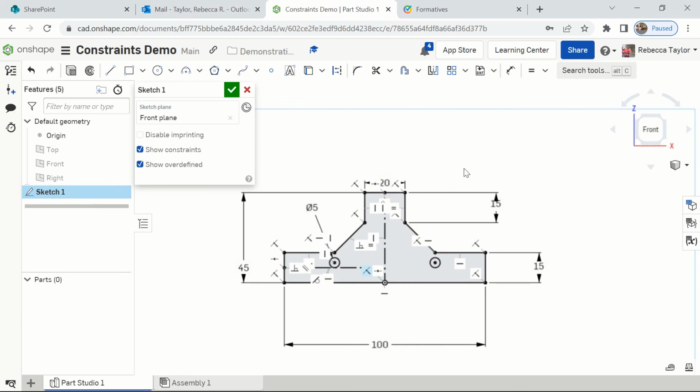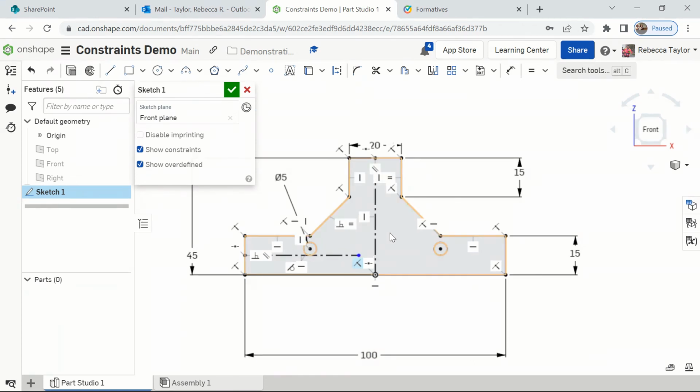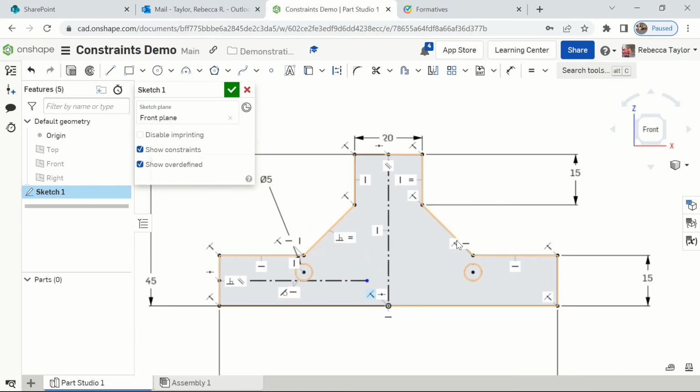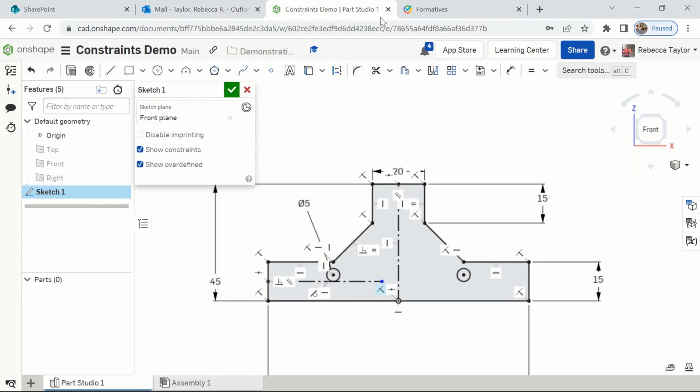You're going to make a couple of predictions about what happens if you change certain measurements in this, and then you are going to change the overall height here to 100. I'm not going to do that because I don't want you grabbing my sketch and submitting it. Once you change that height, go ahead, write your name on it. But notice that everything turned black with that final little constraint on there, and that means that my sketch geometry is fully constrained at this point.